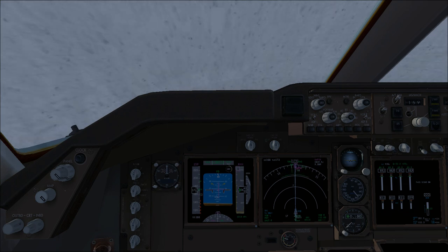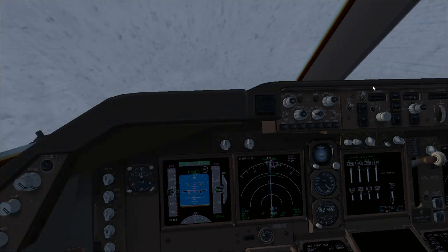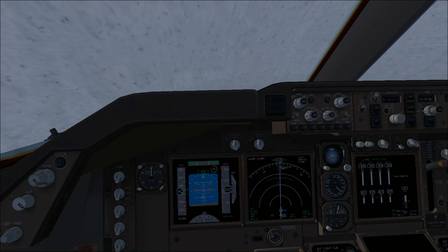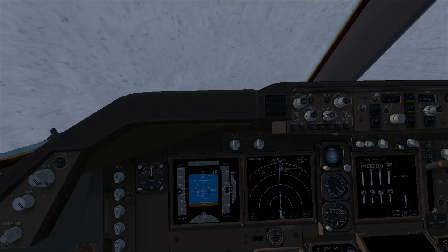And NAV is automatically connected at 400 feet. Please select the command line. And we are now on autopilot. The autopilot is changing to throttle reference and VNAV speed, and keeping V2 +10 as you can see, 165, and flying out from the airport.